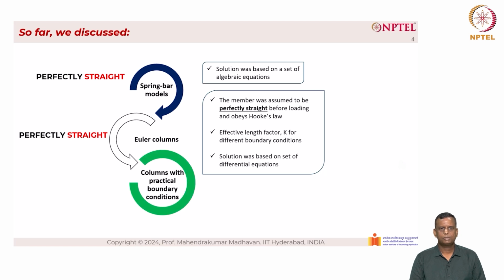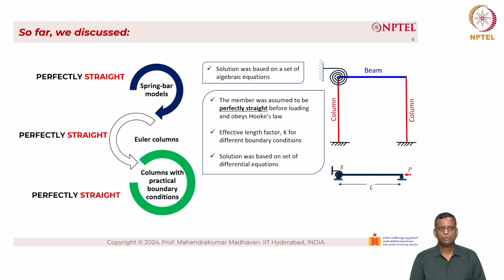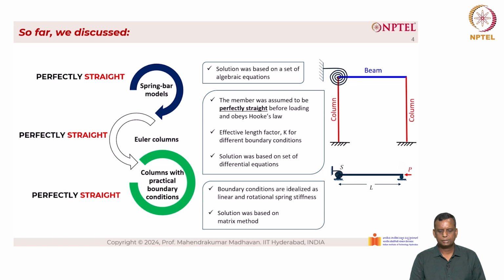Following Euler columns, we also talked about columns with practical boundary conditions. Here also, we assume that the column is perfectly straight. The boundary conditions are idealized as linear and rotational spring stiffness, and the solution was based on the matrix method.